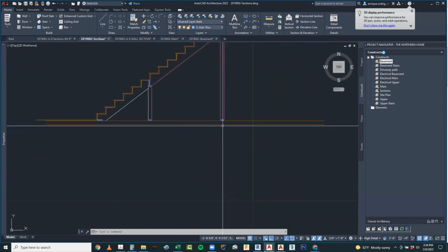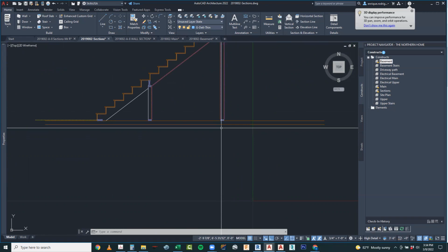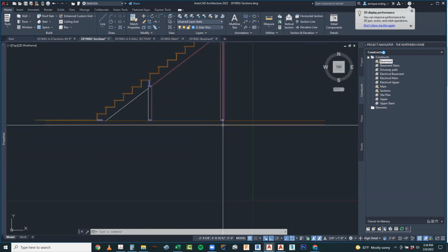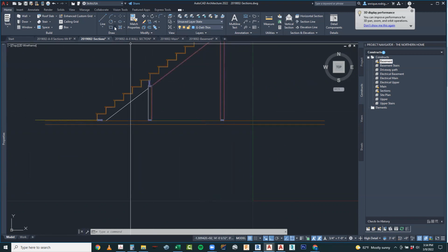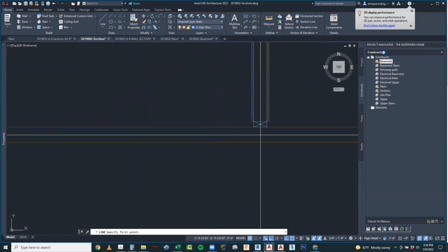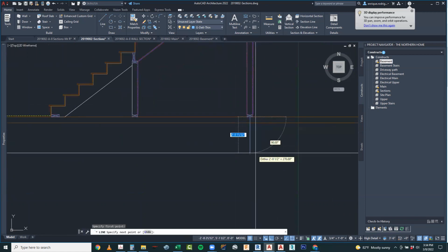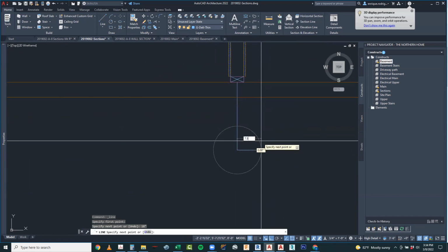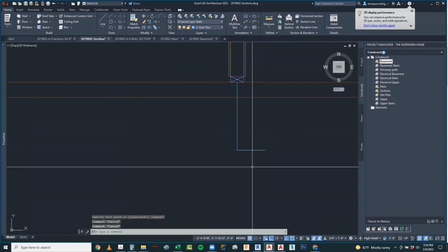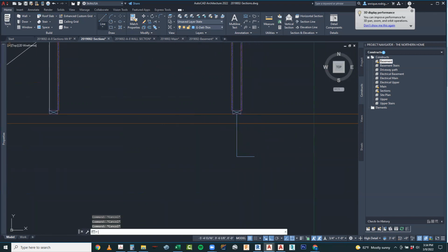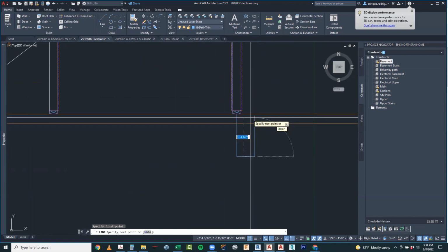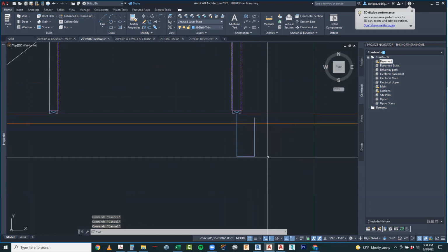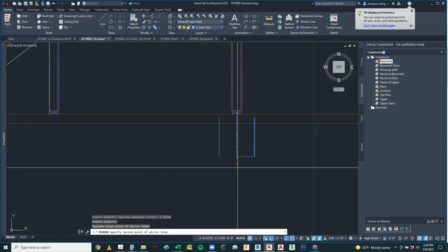You actually need to create another footer in there. I think the book calls for 18 by 15. So it's probably 18 deep by about 15 wide. So I'm going to go ahead and draw a line from the midpoint here. I'm going to go down 18 inches. And I'm going to go 7.5 in one direction. I'm going to go ahead and draw a vertical line in here. And I'm going to mirror that right here.